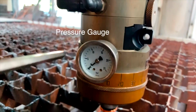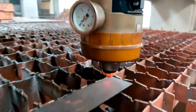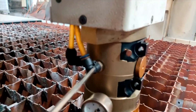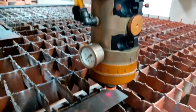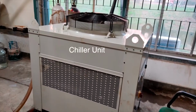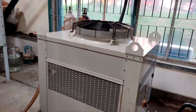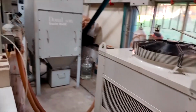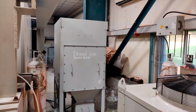This is the pressure gauge helping us to control or monitor the pressure of the assist gas which is being used during the operation. The temperature of the system is quite high, so we need cooling water to cool down the temperature of the laser head. So focusing would be done initially. This is the chiller unit or the cooling unit. Here the chilled water will get generated, and that would be used for chilling the system. Dust collector: whatever dust is getting generated would be collected by using this equipment.